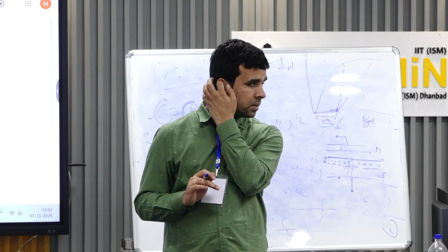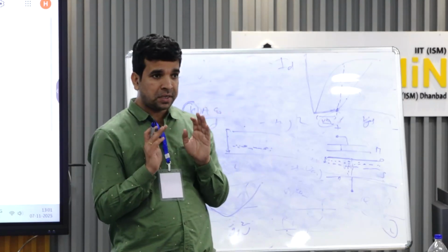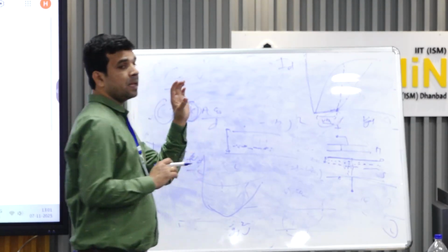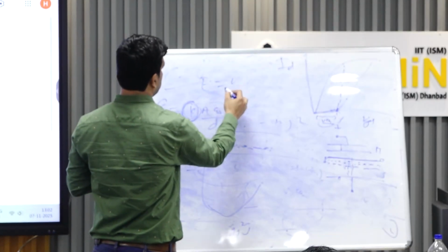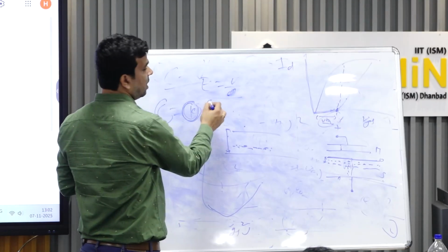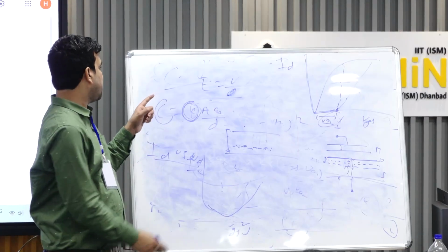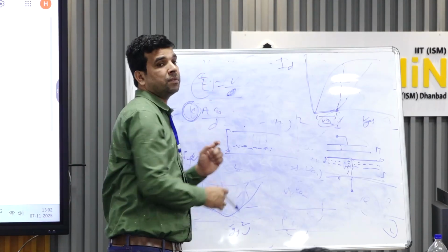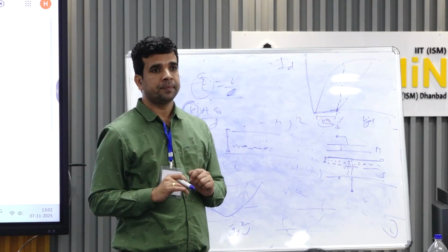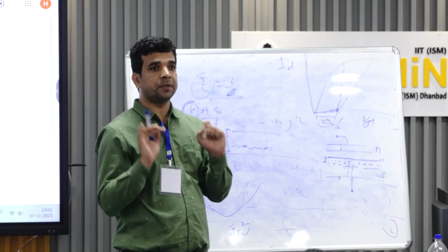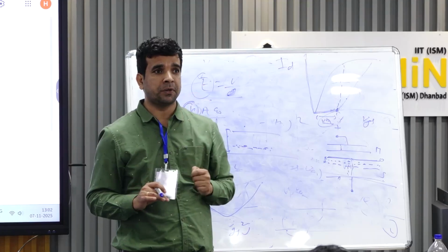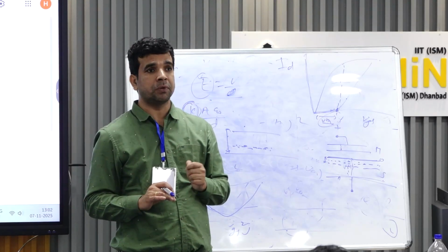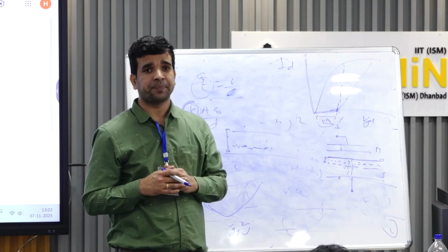Always you have to consider field, so don't just see voltage. Whenever you are applying voltage to any device, always find out the field. See the standard V divided by L, and see whether this field is lesser than the bond breaking field of that particular material. Always be sure about it. When people say okay, 5 volt, they may apply it across a 1 micrometer distance or a 1 nanometer distance, which will break your device.